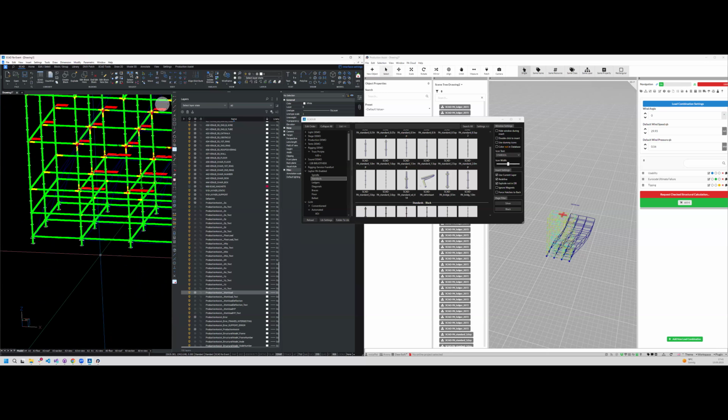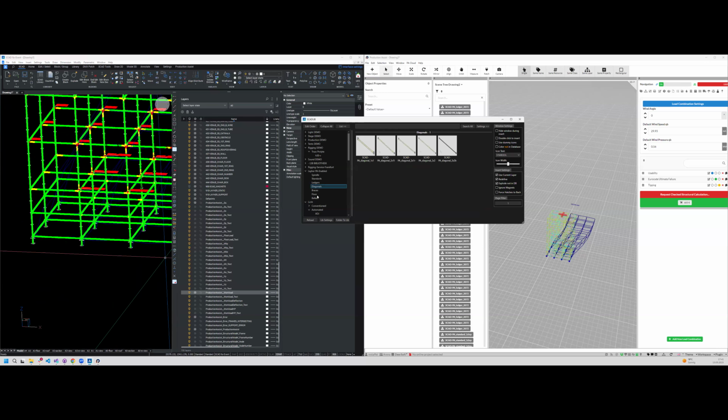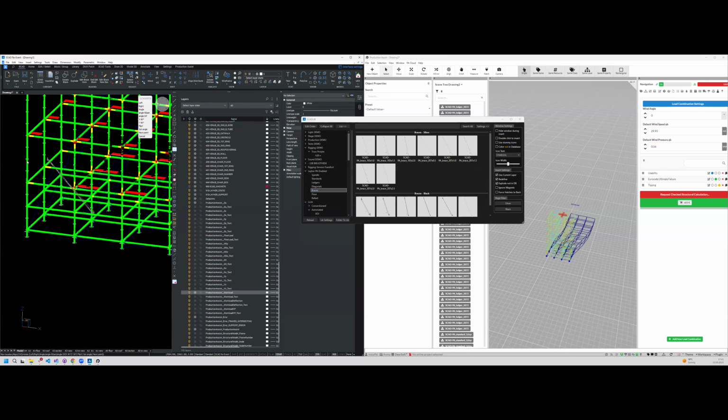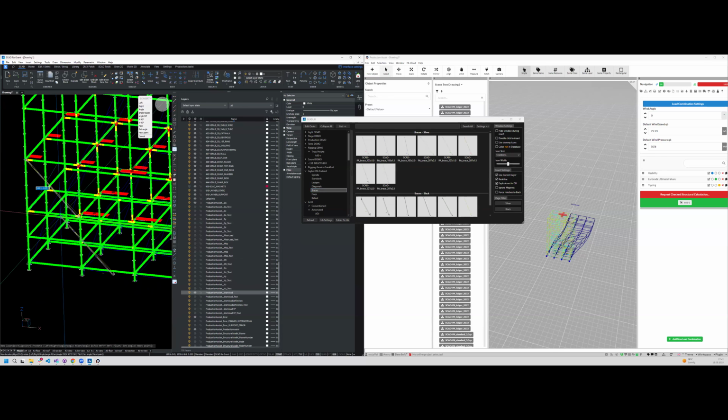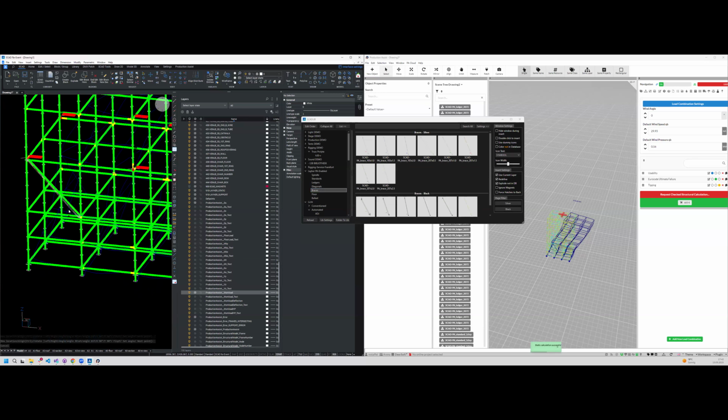What you need to do is insert the diagonals. For the diagonals, you go to the bracings, and there are several bracings. The thing that you need is basically the 207 in length and 2 meters high. If I'm selecting this, I can insert them here with the first one, pressing enter, and you see it does this and changes this in here.